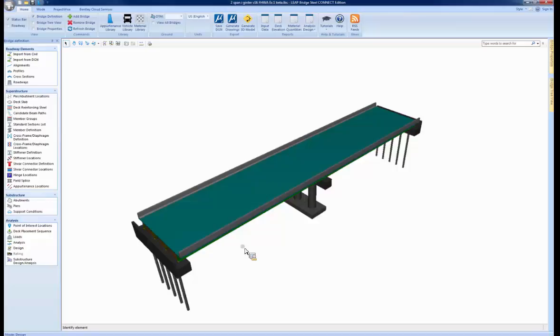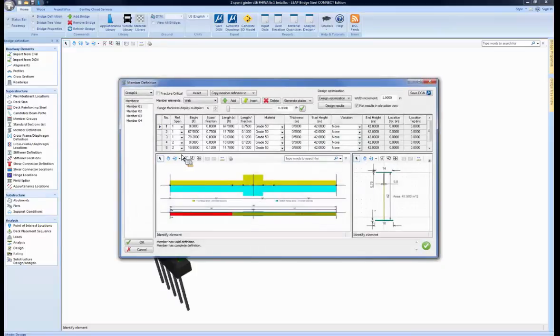Okay. One more here, someone's asking about hybrid girders, if those could be used in this optimization process. Yeah, hybrid girders are taken into account because we do allow you to specify material properties here for the web, top and bottom flange. So you could certainly use different material types there, and those are considered in the code checking as a hybrid girder.